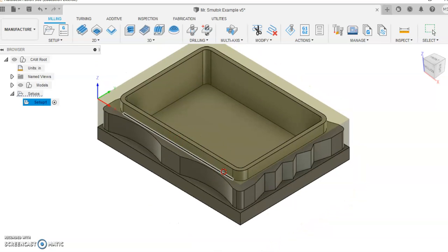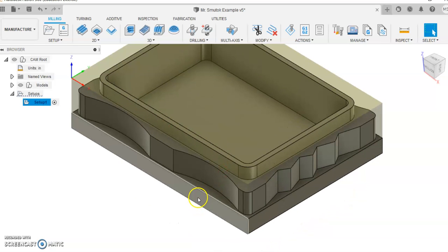Now, I'm not sure if you know, but the reason that I had you only extrude down to this point here is because this little section that I've got the mouse on that's highlighted, we need that because that's what's going to hold on to this while we're machining it. So we actually have to leave a little bit of material that the vise holds onto, or the hold downs on the CNC router hold onto, that aren't going to get machined away.